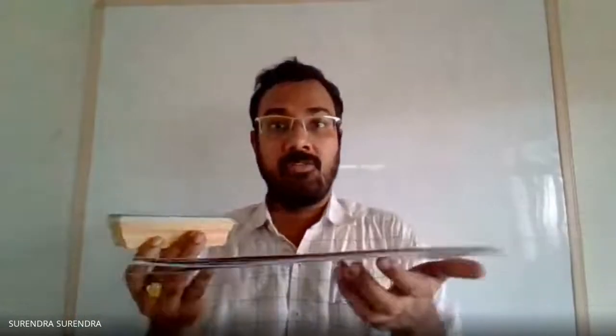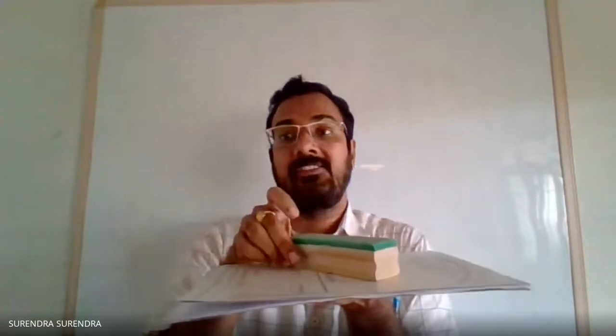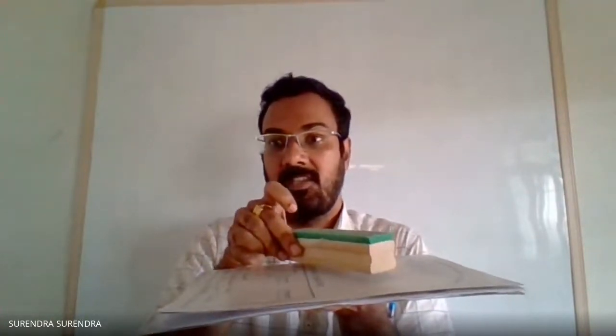If we assume this as the ground, this is the position of the prism. With the initial condition, axis perpendicular to the VP, but it is given as the axis is inclined to the vertical plane. The pentagonal prism is resting with side of base with one of its rectangular faces on the ground, and axis is inclined at 40 degrees to the vertical plane.